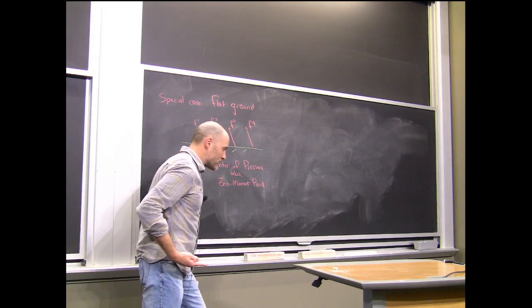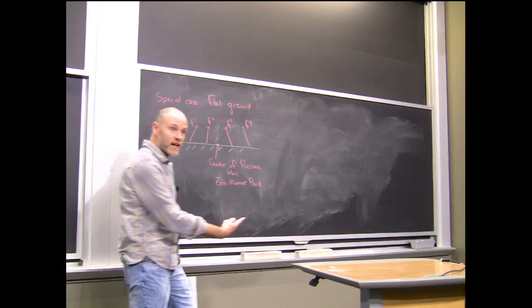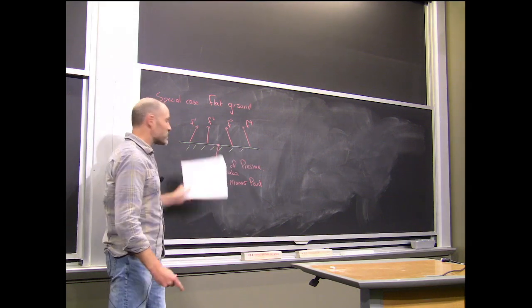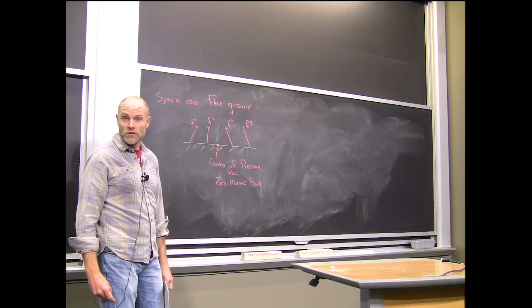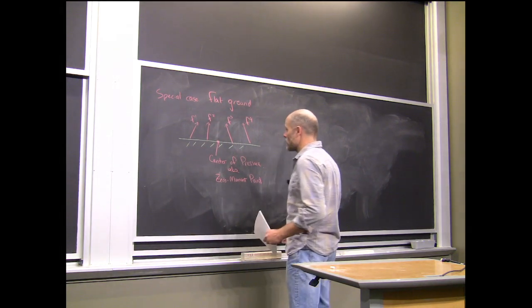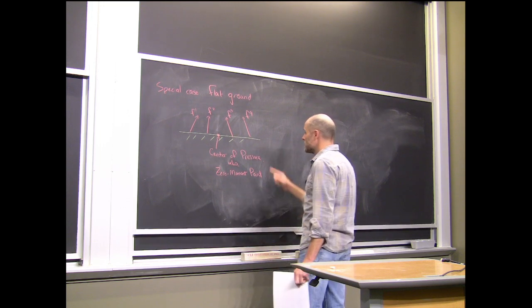So if I'm willing to stick with my z being a constant height, and I just want to know how my center of mass is going to accelerate in the x-axis, then the only thing I need to know is where the center of pressure of that set of forces is. Okay, that's a magical thing which makes all of our planning really powerful. But let's just define it.